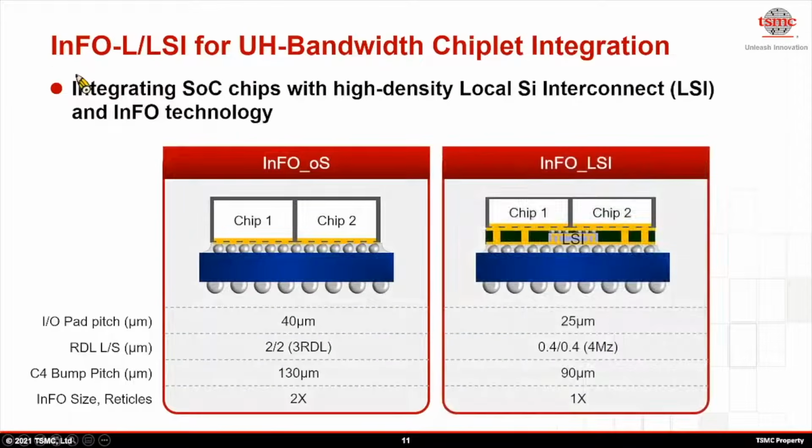To further drive to ultra-high bandwidth chiplet integration, we add LSI, which stands for Local Silicon Interconnect, to our InFO-OS by leveraging both InFO and CoWoS technologies. This new feature drives I/O, pad pitch, RDL pitch, and bump pitch all to new high levels. This solution is available already this year.